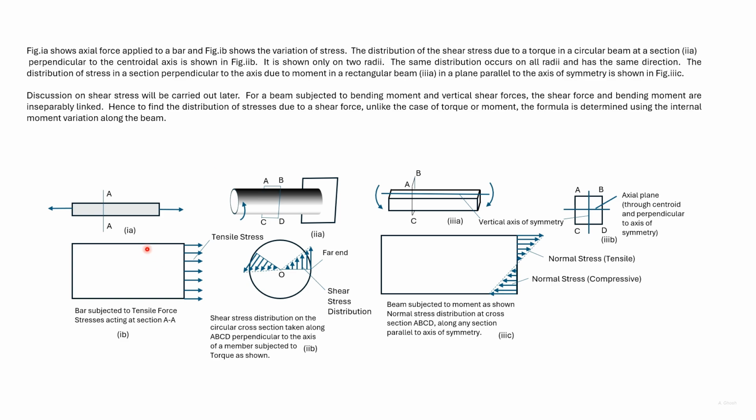When it came to stresses, finding the stresses in a bar subjected to axial load was straightforward. So for a section perpendicular to the axis of the bar, the stress could be defined by dividing the force by the area.